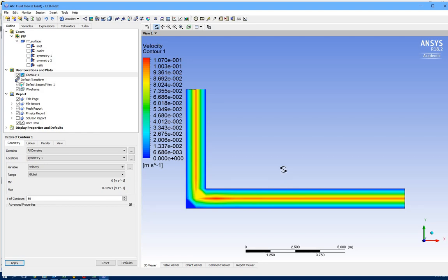I would like to define 2 points here. First of all, for the pipe calculations, usually pressure drop is an important factor, and we have a lot of empirical equations. You can use that if you remember from fluid mechanics, Moody diagrams to find pressure drops.